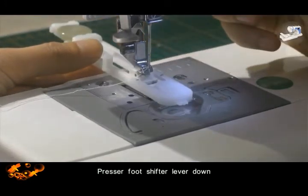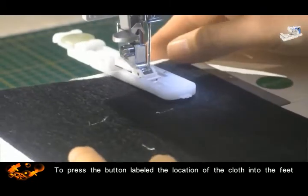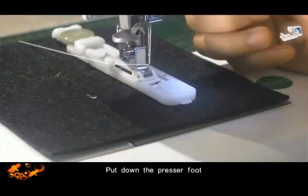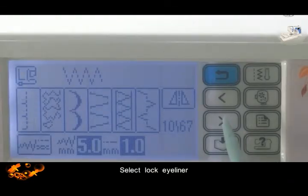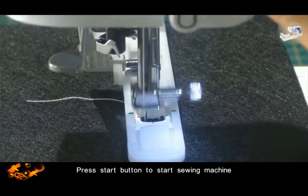Presser foot shifter lever down. Put the cloth into the foot at the location labeled by the button. Put down the presser foot. Pull the shifter lever lock. Select lock eyelet stitch. Press the start button to start the sewing machine.